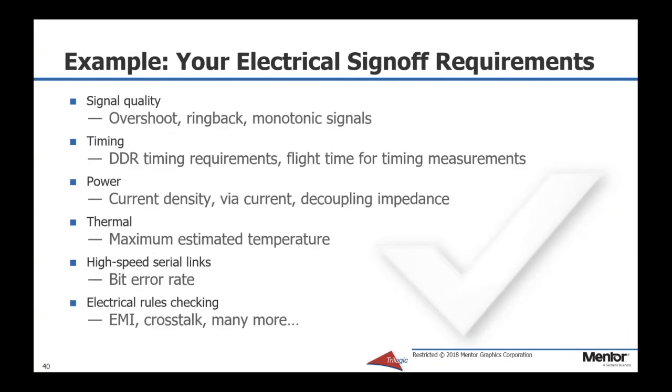For example, now let's look at a subset of the requirements that you might have on your next design. Suppose you know that you will need to meet signal quality requirements for overshoot, ringback, and monotonicity, and the timing on your DDR and other interfaces needs to be checked. You also have to look at the power distribution network for current density and decoupling, and you have thermal issues you need to consider. Simulation of all these issues would be time-consuming.